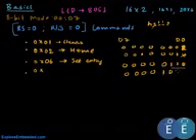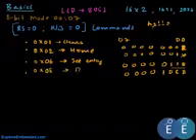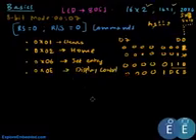If it is 1, then the next bit turns on the cursor, and if you want to blink the character at the current cursor position of the LCD, B should be turned on. Usually we turn on the display, we turn on the cursor, and we do not blink. So that would be 0x0E. This is the display control.